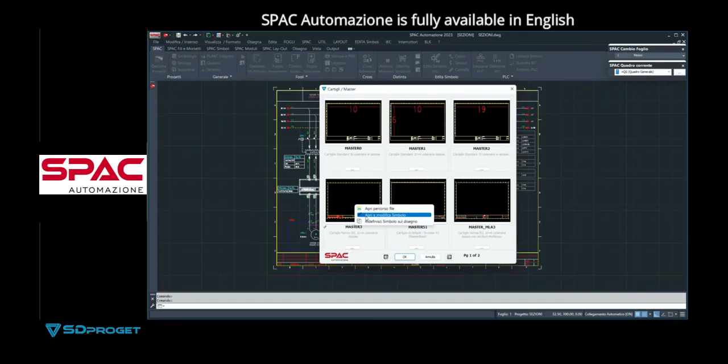It opens the AutoCAD environment for me. Now we will see it with only a part of the menus, those that serve with the custom BLK suite, with the whole series of attributes that are needed. I make the change and accept. At this point, using the very important command, redefine symbol on the drawing, the new cartouche is updated over the old cartouche. The old block is updated with the new block. So if I have 100 blocks of BLK1, they are all updated in one go.